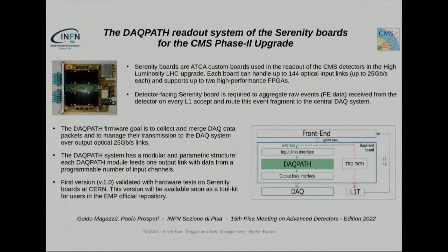And we come to CMS. DAQ-PATH is the readout of the Serenity boards in CMS, which are connected to the level 1 trigger. Each board has 144 optical inputs with 25 gigabits. It's a modular design, and it has the possibility for flexible configuration to meet the timing requirements.